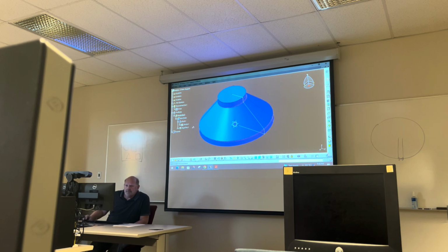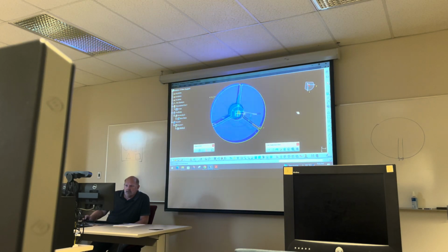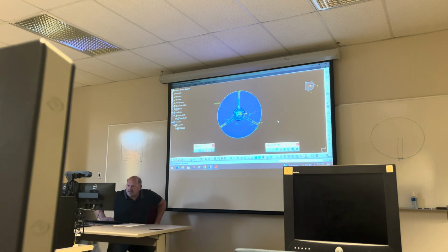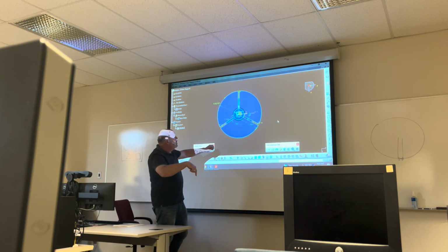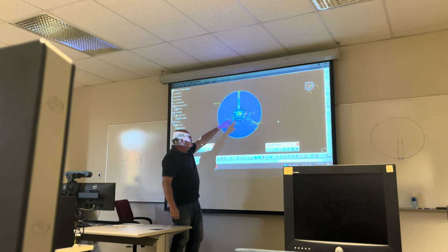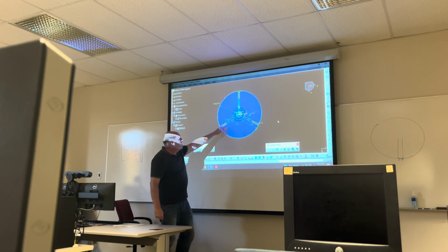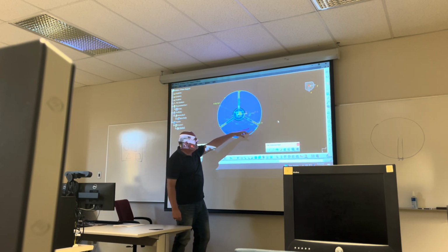And here are the pockets. Let me show you what the sketch looks like for those. This is the part that a lot of people struggle with. But if you think about it as simple geometry, in plan view, you're looking straight down at the top. You're using this as your center. You have one line going straight up, and then these are 120 degrees, and then these are offsets of 6 millimeters. So if you put a reference element in here and offset it 3 mils on each side, that'll give you that piece.